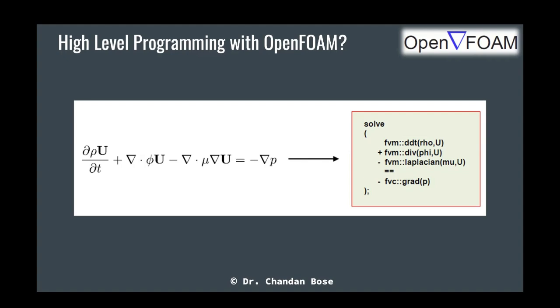I hope you have all done CFD courses, you understand that. So if we want to write the temporal term or the unsteady term, we directly use ddt. ddt is the function which does the temporal derivative, depending on what type of discretization technique you have defined in the fvSchemes. In the fvSchemes, you have told OpenFOAM that when we use the ddt function, you do Euler discretization, which is first order accurate, or you can do Crank-Nicolson type of discretization, which is fractional order accurate, etc.